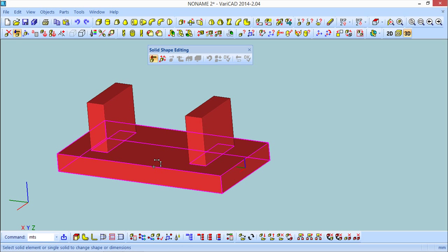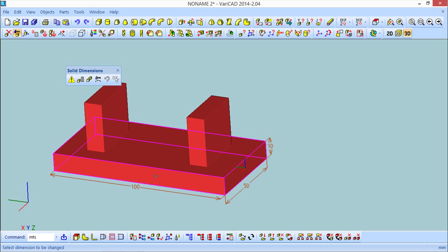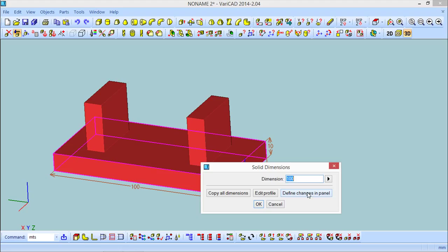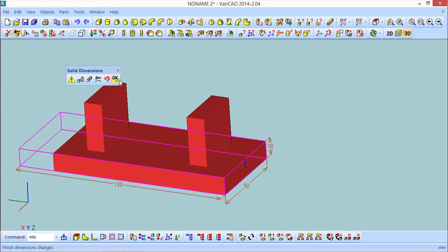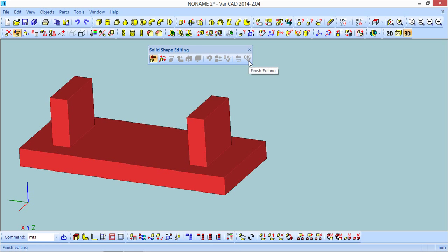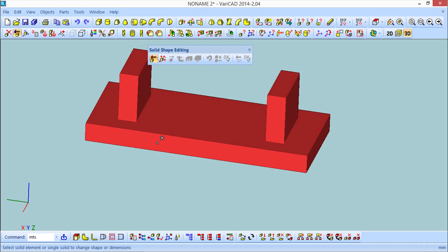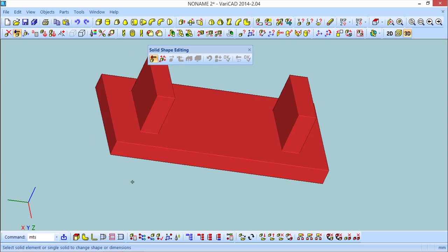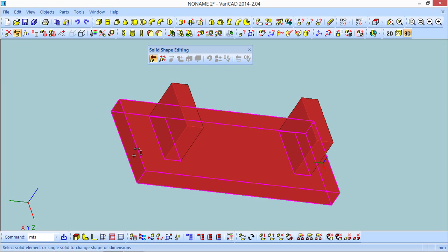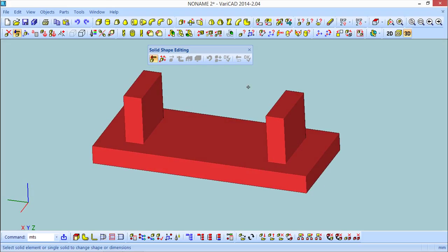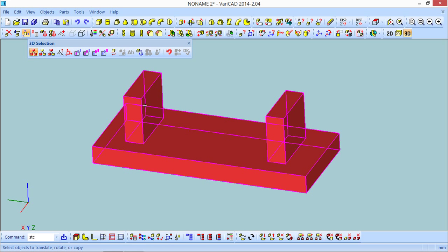What I can get now is, if I try to edit this solid on the dimensions, you see on this dimension, because they are constrained in this direction, if I edit this dimension here, for example 120, what happens is the model is updated, and because it was updated in this direction, these remain equal, and the root solid changes, and this is still respecting the constraint we've defined of 20 from this patch to the insertion point of this solid here. This is the basic of the constraints.